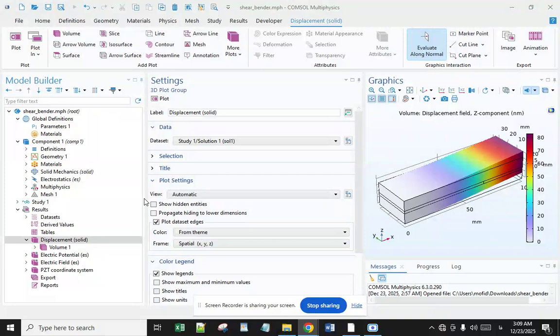In order to examine the convergence of the present element, in this case for the shear actuation mechanism, there is no rigid form since the piezoelectric actuator occupies all the core layer. For both mechanisms, the deformation of the continuous actuated cantilever beam was computed by only four finite elements. Comparisons of these results to the analytical solution are presented in this simulation, indicating that finite element results for the deflection of the shear and extension actuated beam matched very well with the theoretical solution.